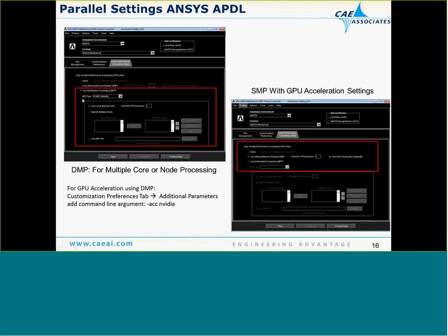And for the MPI type, again, it just depends on which libraries you want to use, but in general, what we have found is PCMPI, the default selection, works fine, but your computer may experience a slight benefit using Intel libraries, for example, if your computer's been optimized with Intel compilations. My recommendation to you here is just to try each to see if you notice a different scalability in your runs. But in general, even if you do, it should be on the order of 10%, likely not more than 20%.